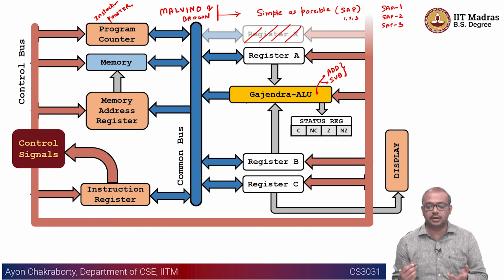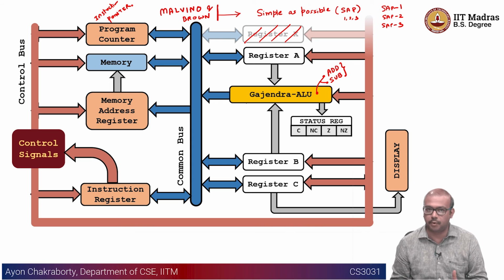So this is also an Intel terminology. Intel computers often have this particular entity, which is equivalent to the program counter. They call it an instruction pointer, which is logical, right? The instruction pointer is typically pointing to that instruction, and in essence, it is storing the address of a particular instruction. So it is actually a pointer, right? The instruction pointer points to a specific address in the memory, and the value is going to be stored in the instruction register, which is the actual instruction.